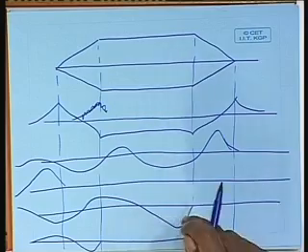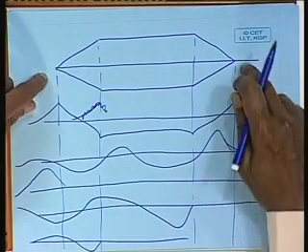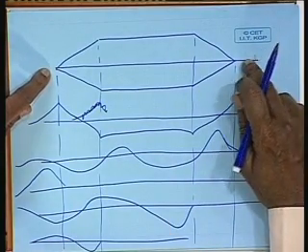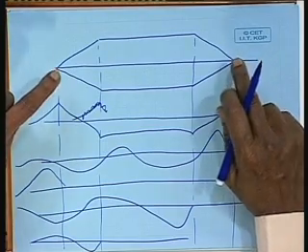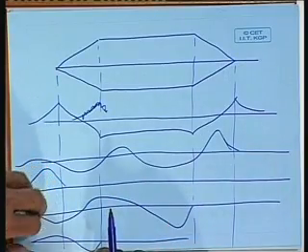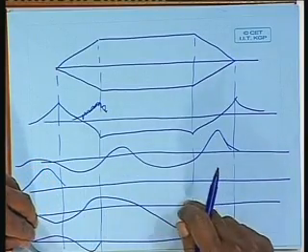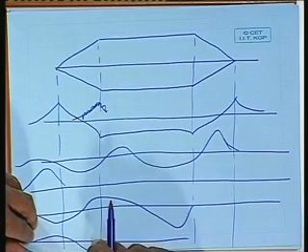So, you will have 4 wave systems. The most prominent ones are the forward wave and the stern wave, with crests being generated at the forward end and stern end, and the shoulder waves generating troughs at the forward shoulder and aft shoulder will also be there.